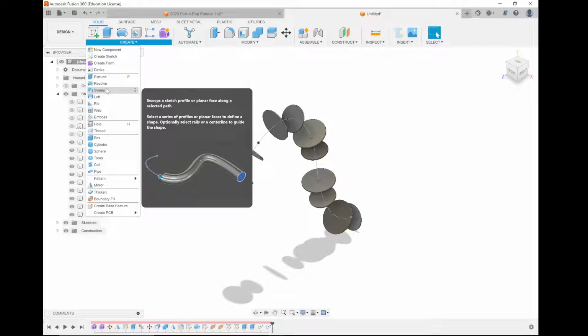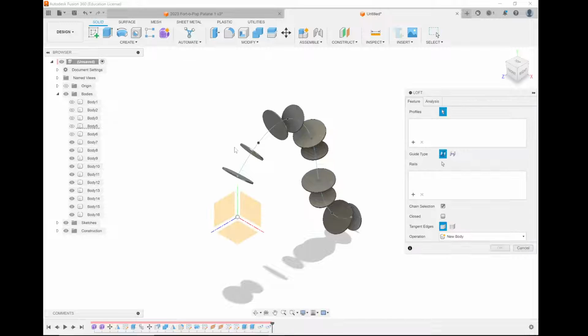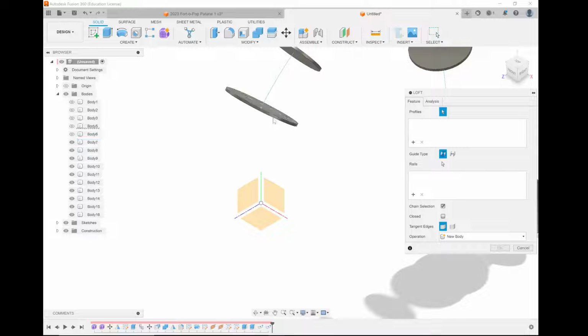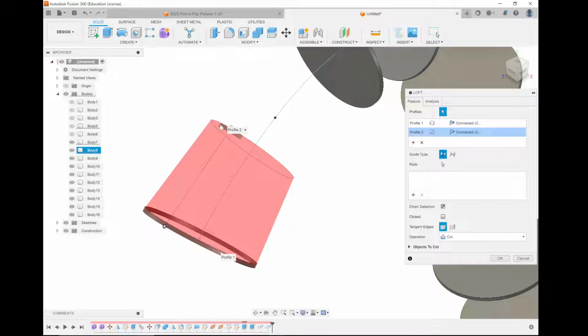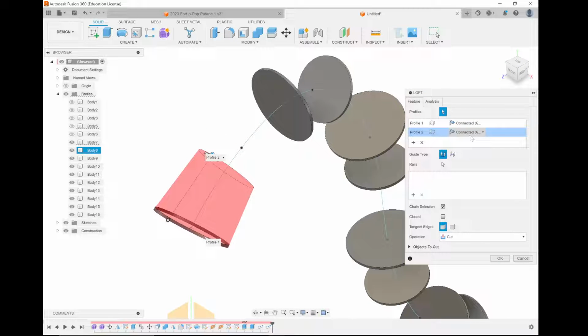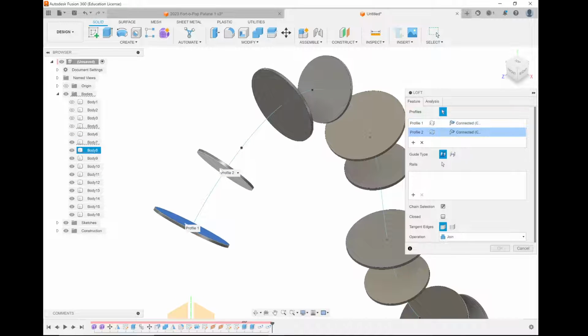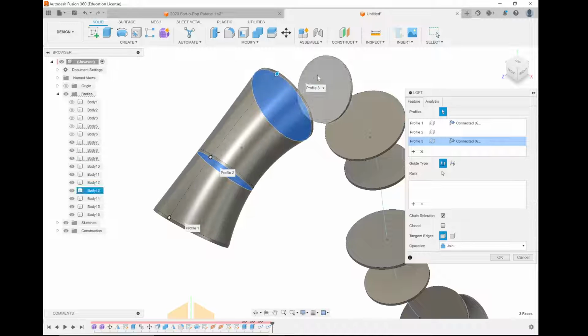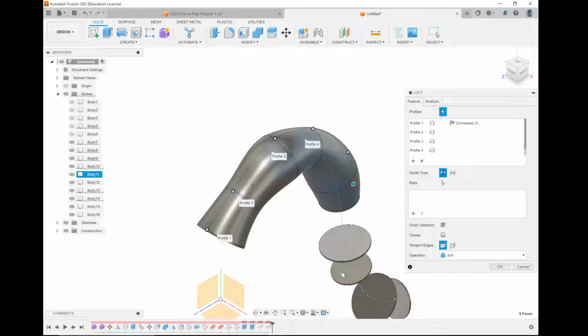We're going to be using the Loft function. The Loft function gets a selection of profiles and turns it into a 3D object. So we press Loft, and now all we have to do is select all of our faces. Hold on, that's not what we want. Create Loft. Oh yes, we just got to press our faces, and then press all our faces along our shape.